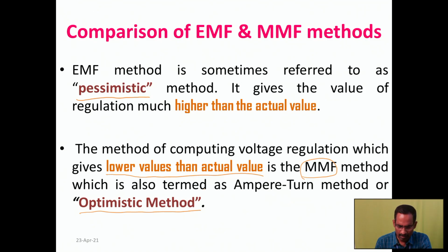method. Normally, if we have any issues in our health, if anybody is consoling us, saying it will be all right within a few days, he is giving positive energy for us. So like that, here the MMF method gives the voltage regulation which is lesser than the actual value, so it is called the optimistic method.